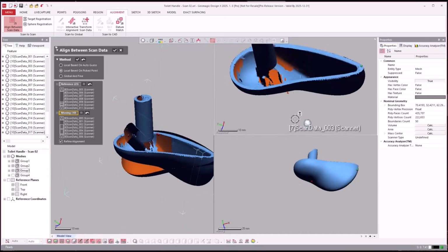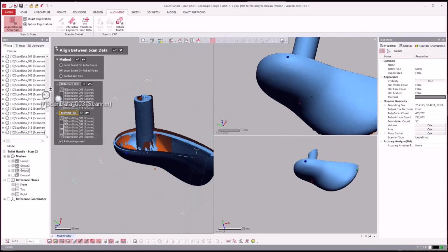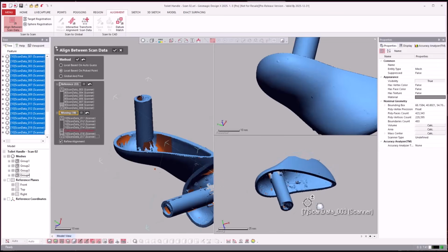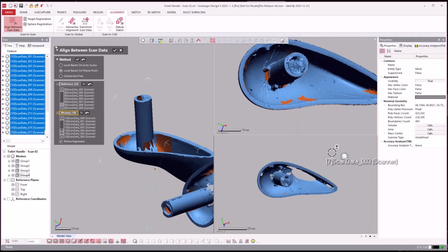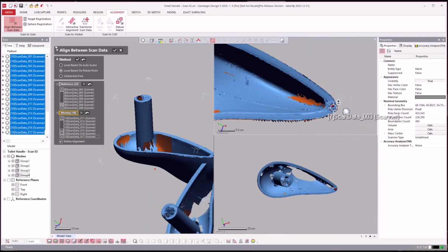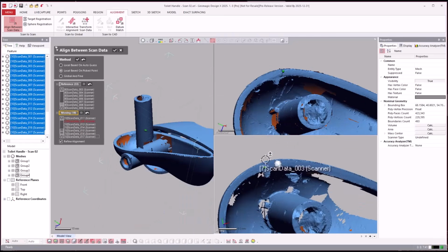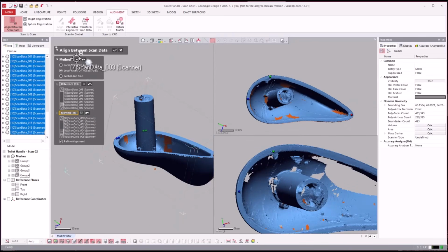And you see that I'm trying to spread out the points across. This has a lot of curvature, but I get them somewhat spread out, eyeball them, and then you see parts with lots of curvature like this. It's kind of easy to align them and lock them in. You have to mess it up in order to get it, because I already have lots of overlap. We already see that. I probably scanned it even more than you needed to, so not a big deal there. But you always kind of have more scan data than normal.